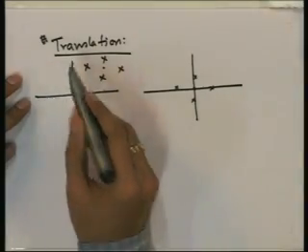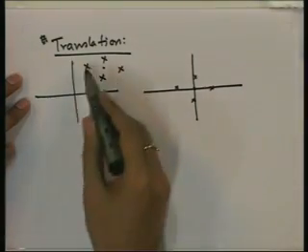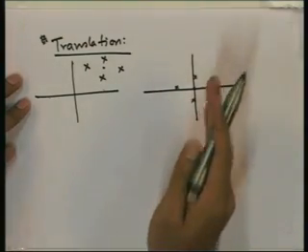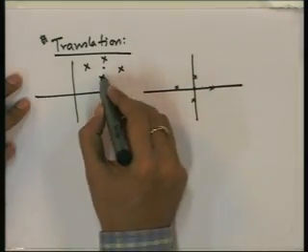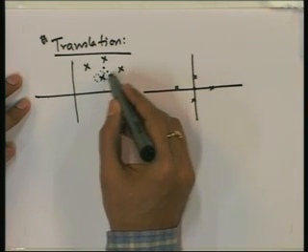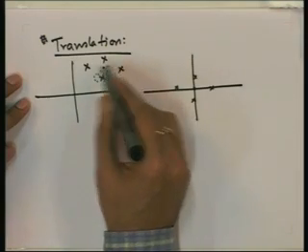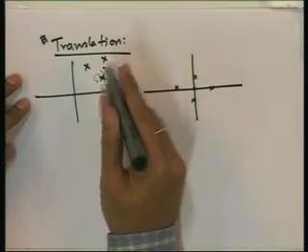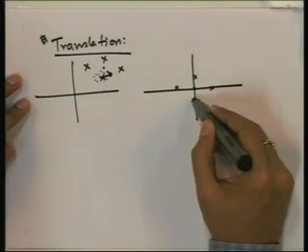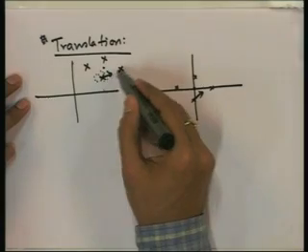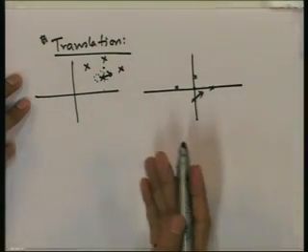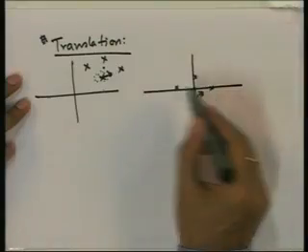We can also feel that the performance of the signal set here and here will be the same. How do we see that? If this signal is transmitted here and it is corrupted by noise, it will go here. The probability that the noise is so much that it will bring the point nearer to other points will be the same. The same noise will deviate this point to here. So, if this comes near, this point will also come near for the same noise. So, the probability of error here will be the same as the probability of error here.